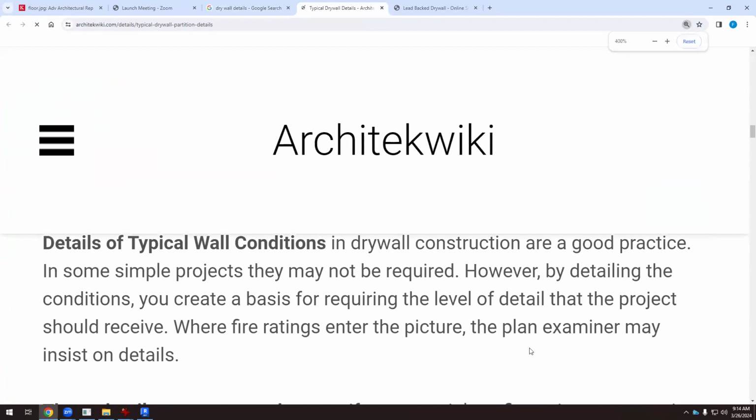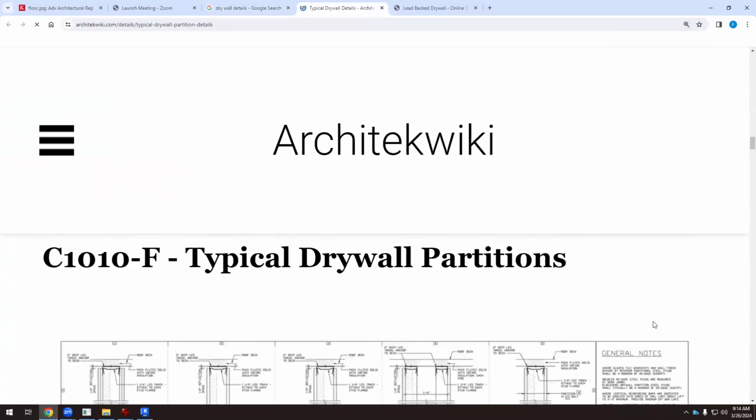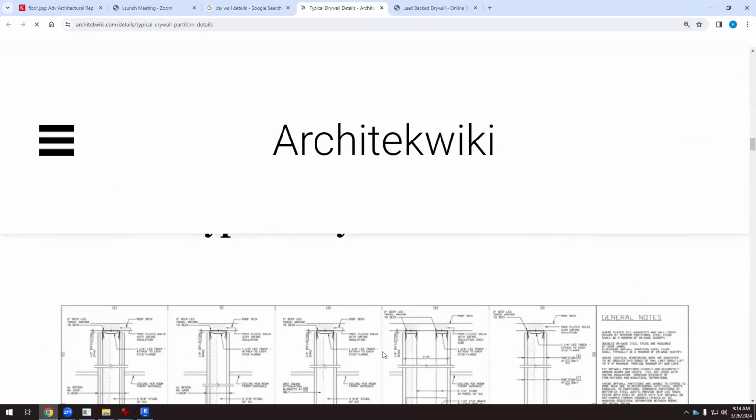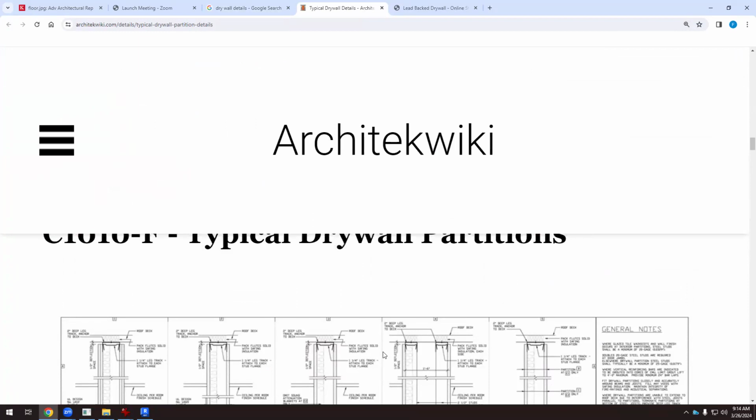If we look at these drywall details, you see that we have this element, and then we have the wall here. If we want acoustic insulation, we can fill this gap between the two drywalls with glass fibers or something that absorbs sound. And probably in between the two classrooms, we will have that.